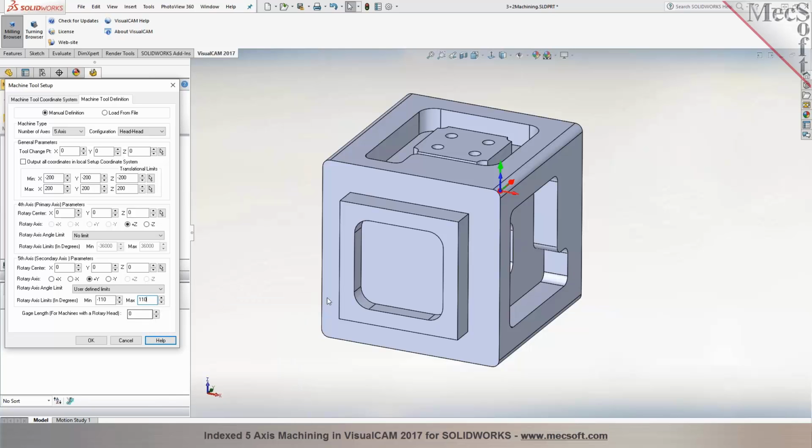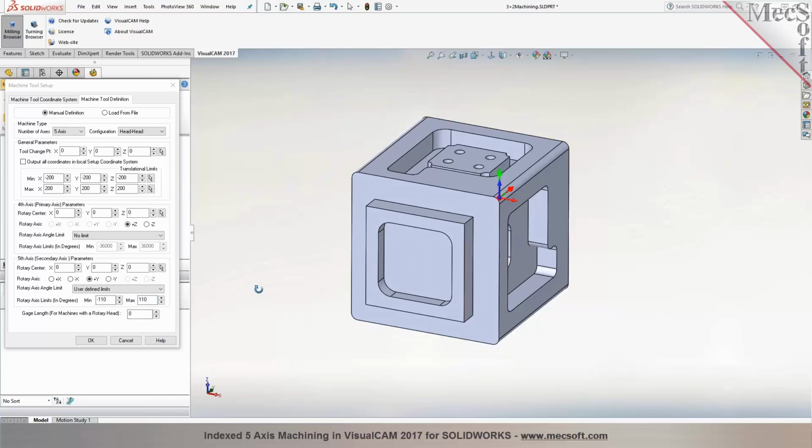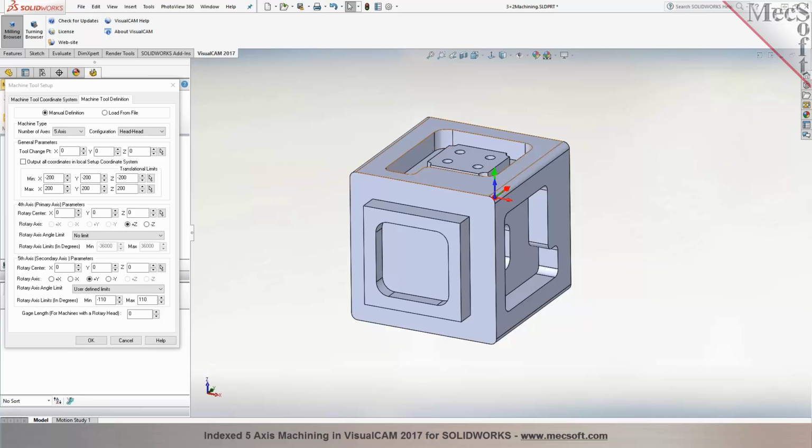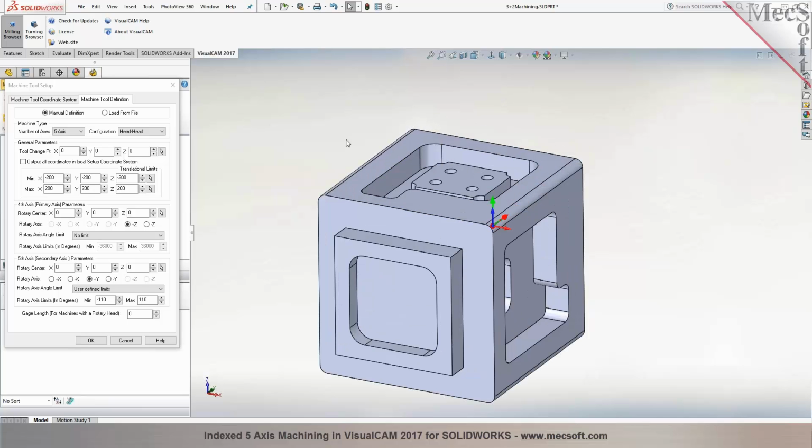And I have to check really well the features of the machine in order to set correctly those degrees and those features there in RhinoCam. Right. If you look at the machine tool specification provided by the machine tool vendor or manufacturer, they would tell you the rotary axis limits of primary and secondary, and they will provide you with most of the information.